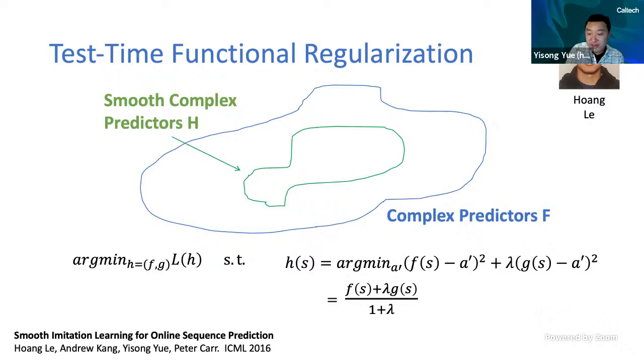So basically what this is saying is that at every time step that I'm making a prediction, I am predicting an action that doesn't deviate too far from the action of G. So that approximately preserves this local behavioral constraint. And you could show that in certain cases you can also invoke forward invariance, like Lyapunov stability. So that's number one. Number two, in order to get this to work in practice, of course, the time discretization needs to be sufficiently small.